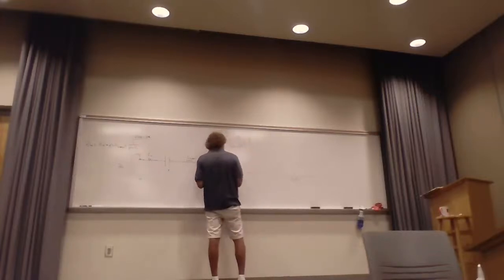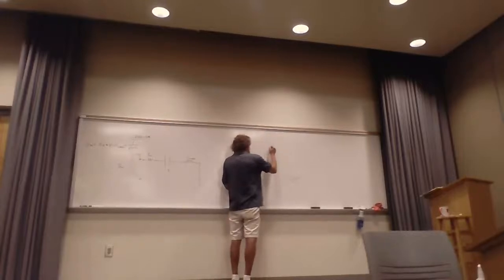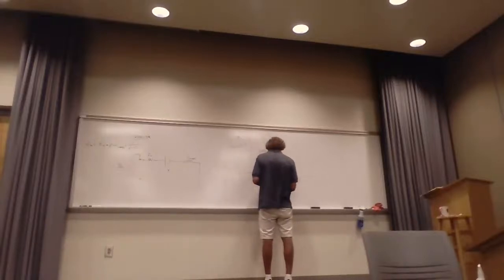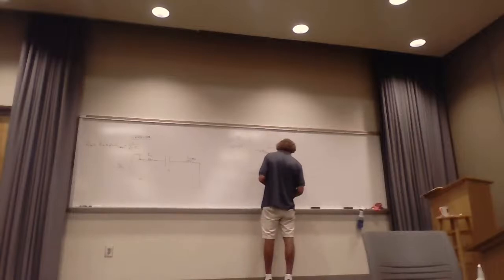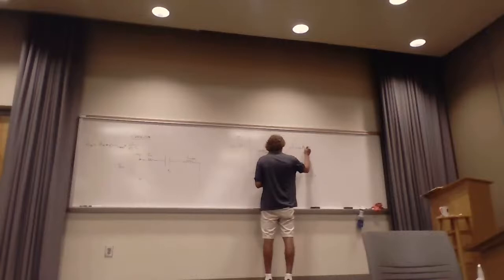And for this one, it's a capacitor. It's coming in from infinity. It's got a rate of minus 20 dB per decade here. Then it hits the self-resonance frequency, which is 1 over 2 pi square root of LC here, and that would be the L in the lead and the C. And then after that, it'll start going up at positive 20 dB per decade.